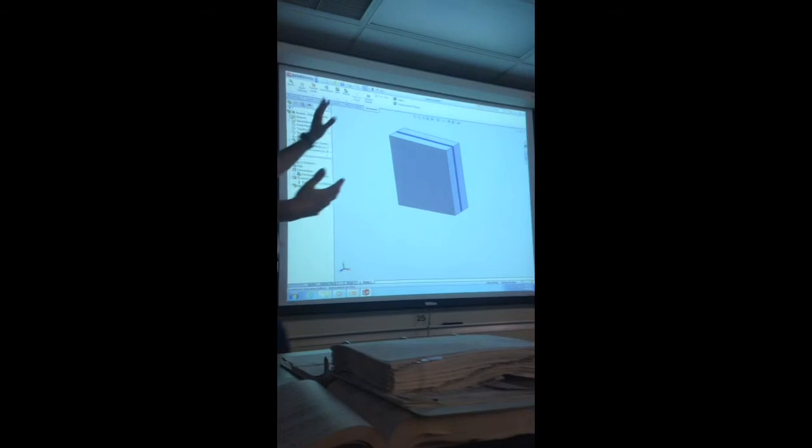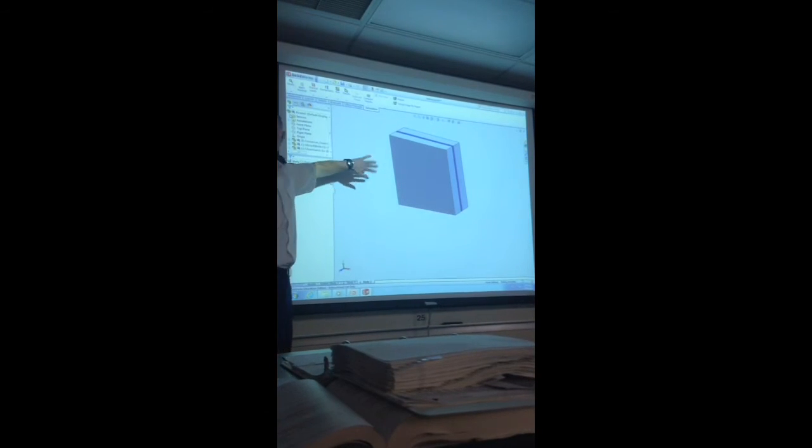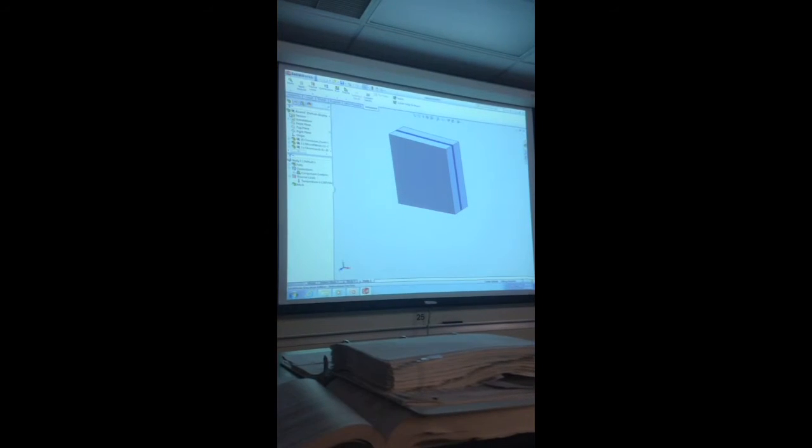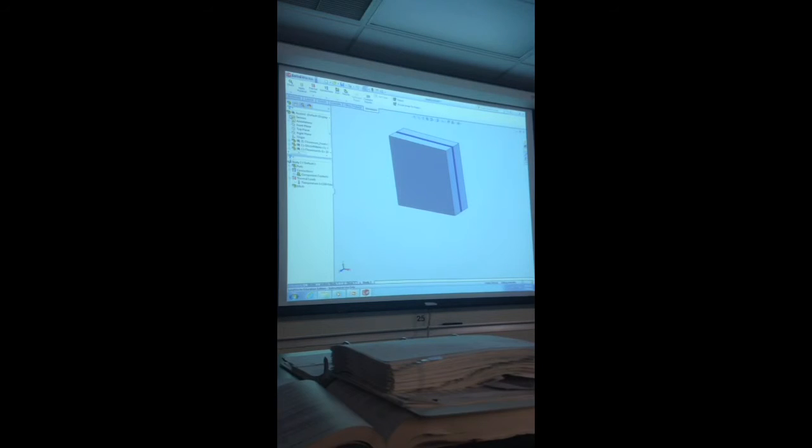Now, what are our other thermal loads? Without taking the time to go through them, what else do I want to apply on this? Corner symmetry. Convection. What about the very top? Insulated at the top, right? How about far away from the laser on the side? Over here. That whole side, not just that one edge, but 3 edges, right? 2. There's a depth here we're talking about now. How about that side? What do we say about that? Also insulated, yes. How about convection across the whole front face?